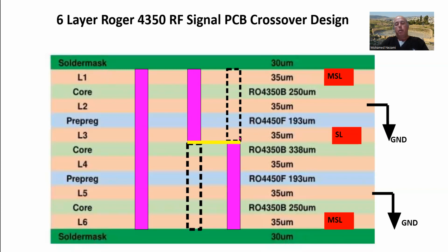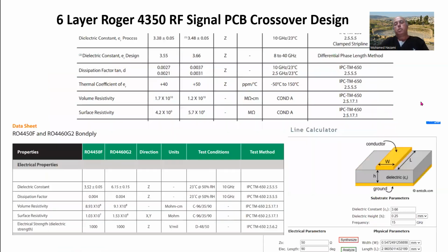Now, either way, there's an additional piece of the via that is hanging there as an open stub. And open stub, of course, is a passive component, and that impacts your signal, and that could kill your signal.